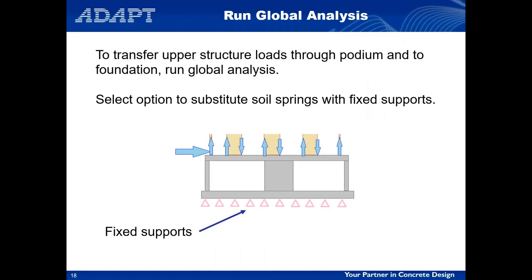So now we have our model adjusted. So now we're going to run the global analysis, and we're running the global analysis because we now want to take all of those loads, superstructure and the loads that we just talked about defining for our concrete podium, and take those to our foundation and to our walls.